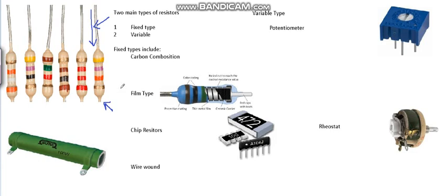Now, having said that, if we take a look at a resistor that is perhaps this size, and if I have another resistor beside it that is perhaps bigger, but it's also rated for 100 ohms, and perhaps this is a half watt resistor, and perhaps this is a 2 watt resistor. So they'll both have the same ohmic value, the ohmic value being the nominal value that is being manufactured to, that specification that is being manufactured to. So they both are good for 100 ohms.